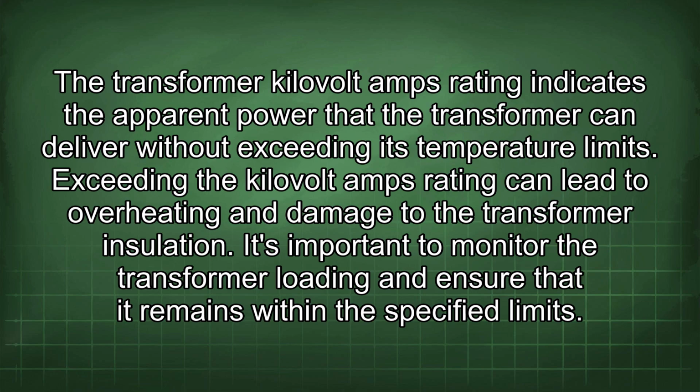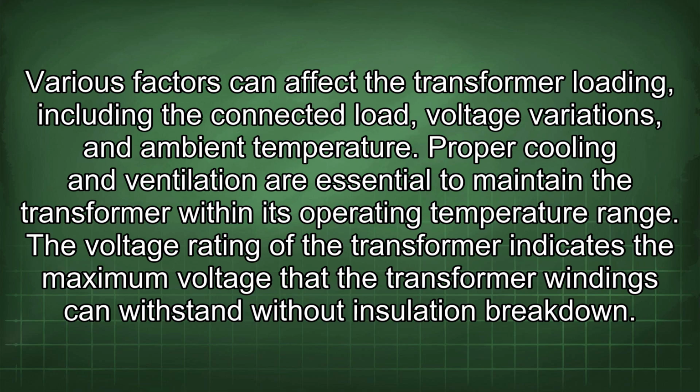The transformer kilovolt amps rating indicates the apparent power that the transformer can deliver without exceeding its temperature limits. Exceeding the kilovolt amps rating can lead to overheating and damage to the transformer insulation. It's important to monitor the transformer loading and ensure that it remains within the specified limits. Various factors can affect the transformer loading, including the connected load, voltage variations, and ambient temperature. Proper cooling and ventilation are essential to maintain the transformer within its operating temperature range.